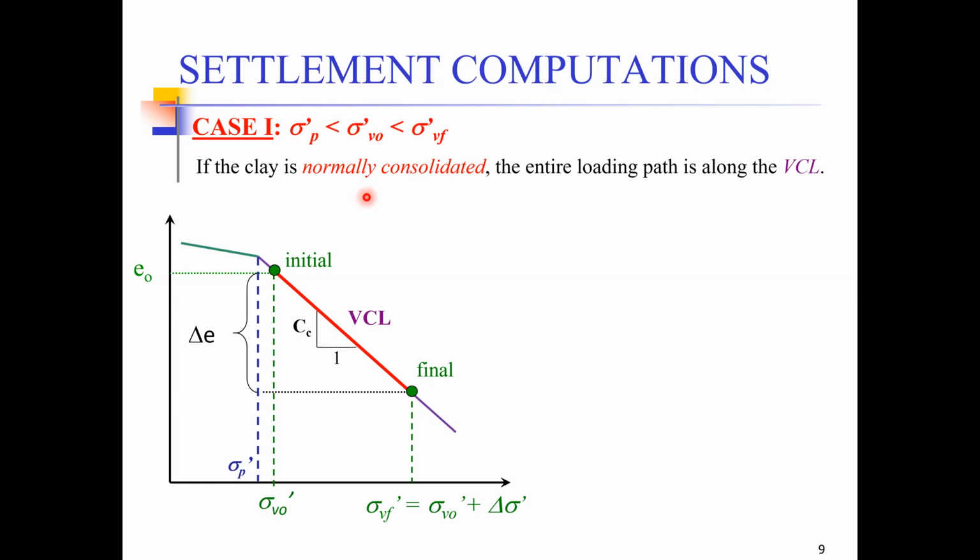If I ask you what is compression index, you would tell me compression index is the slope of the virgin compression line. Okay, what is the slope of the virgin compression line in this case? The slope of this virgin compression line would be this ordinate or y-axis value divided by the x-axis value, which can be written something like this. So Cc equals this delta E.